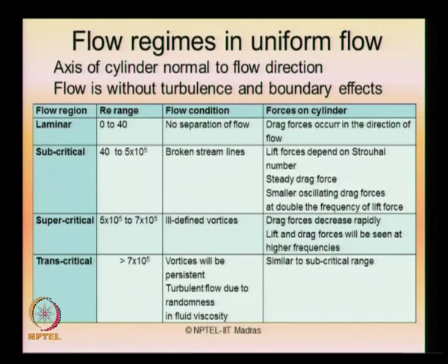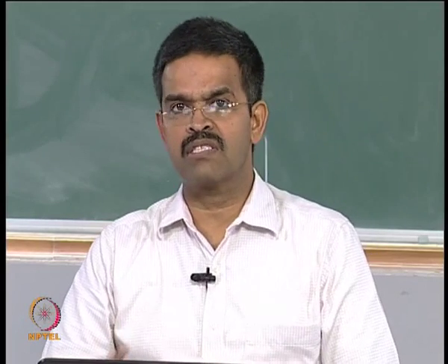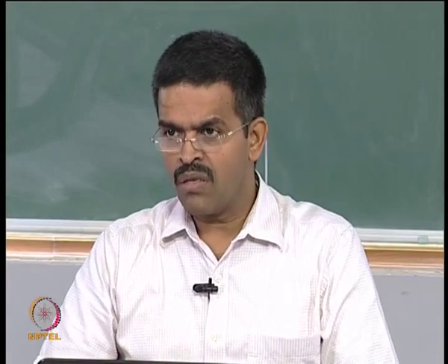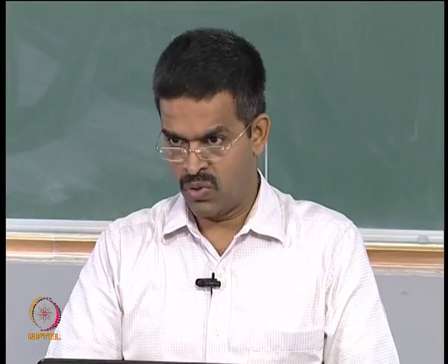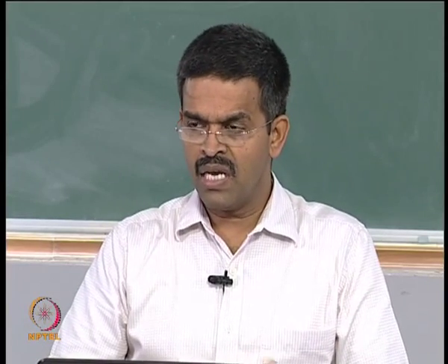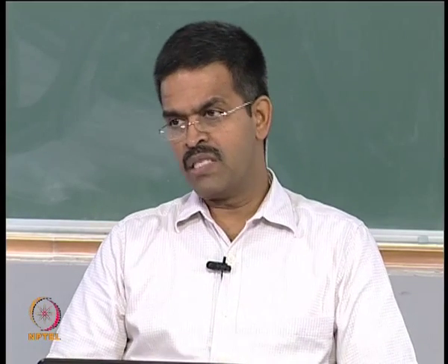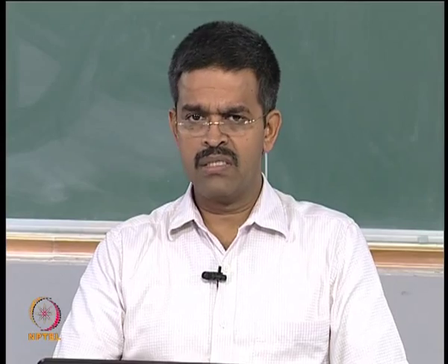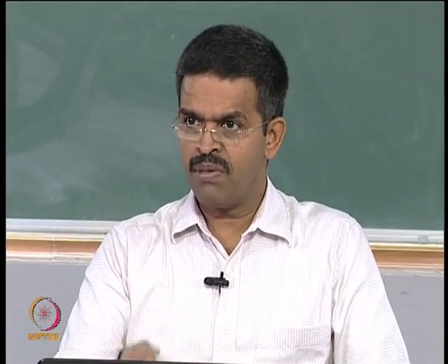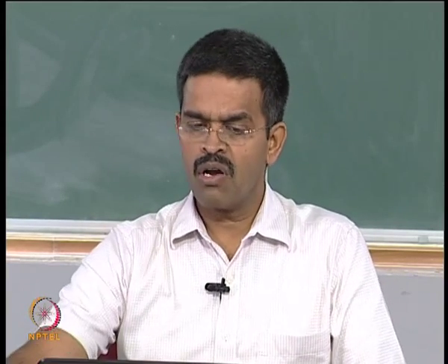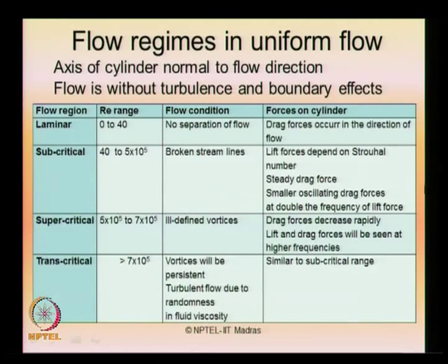Now what we are interested in, as I said in the beginning, is that my aspect of discussing marine structures will be only on the force exerted on the system, or the response given by the system back to counteract these forces. I am not interested in discussing in detail the hydrodynamic part of the force on the system, because we are talking about marine structures, and as a structural engineer I would always address this problem in terms of either the force received by the structure or the response given back by the structure to the environment. So let us talk about the effect of these regions in terms of the forces on a cylinder whose axis is kept normal to the flow direction.